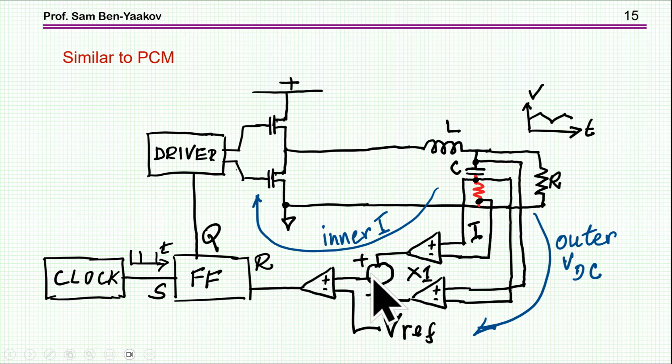Well, it's not that much, but still it is sort of moving away, and the average is not 5 volt as I would have liked to have, okay? So this is a problem that we have when we have the slope compensation, and in fact it is a problem with the method itself, because it's looking at the peak and not at the average.